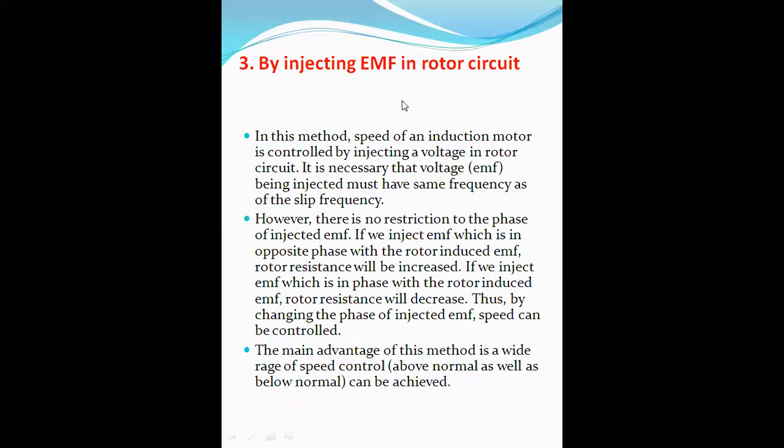Another method is by injecting EMF in the rotor circuit. In this method, the speed of an induction motor is controlled by injecting a voltage in the rotor circuit. It is necessary that the voltage being injected must have the same frequency as the slip frequency. However, there is no restriction on the phase of the injected EMF.